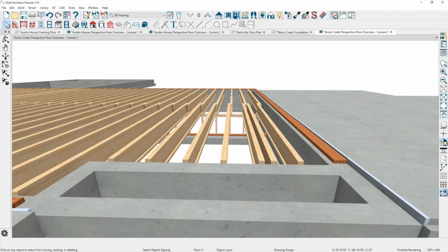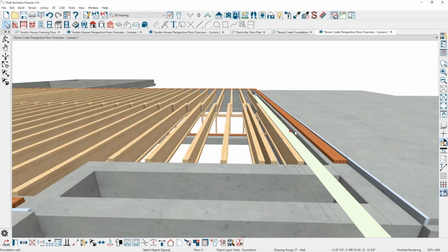So can I ask you then, can you just select that wall that's between the mono slab and the existing foundation, select that particular concrete stem wall and uncheck that? And that one will change, I would think. It might. There are several walls in here that would affect the framing, so I would probably go through. That's sort of my point. The stem wall is existing, and then I come back in, I manually build the slab, and that's where I'm having a problem. Okay. Why don't you send it in, and we'll just take a quick peek at it.